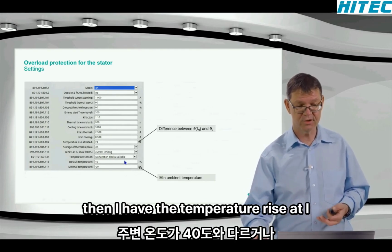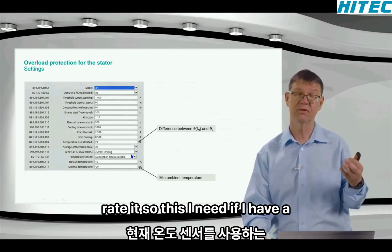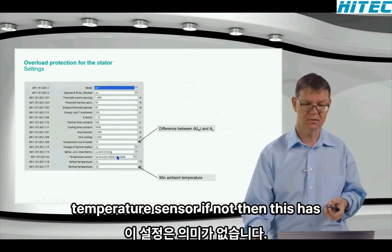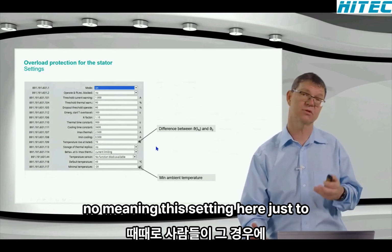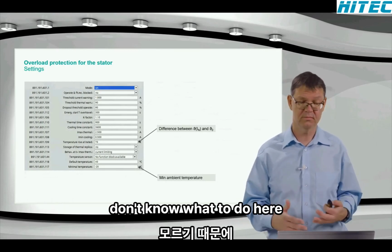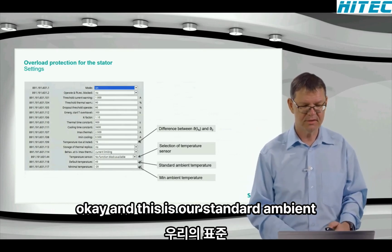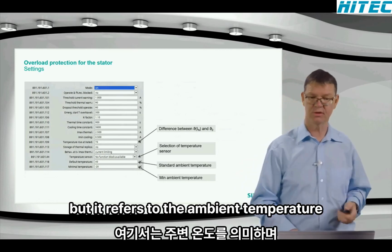Then I have the temperature rise at I rated. This I need if I have a different ambient temperature than the 40 degrees, or if I use the current temperature sensor. If not, then this setting has no meaning, just to mention that, because sometimes people don't know what to do here in that case. This is our standard ambient temperature, called default temperature, but it refers to the ambient temperature here.